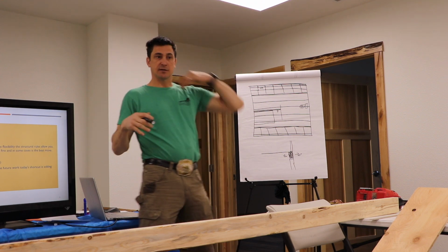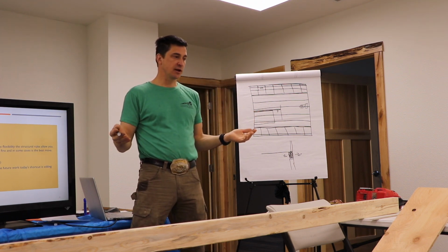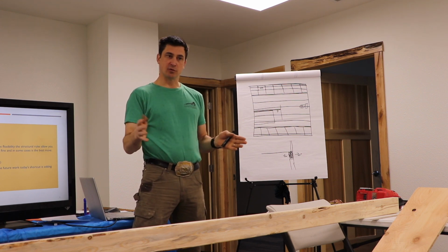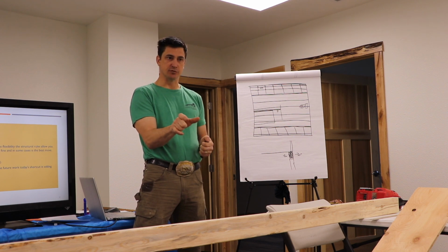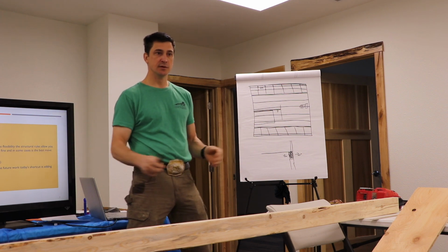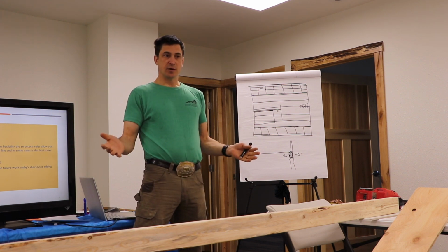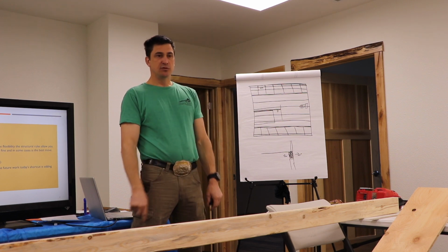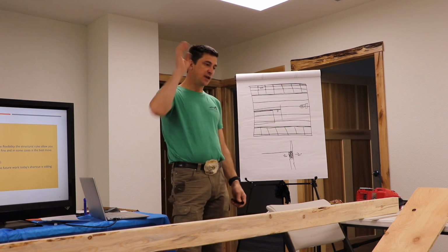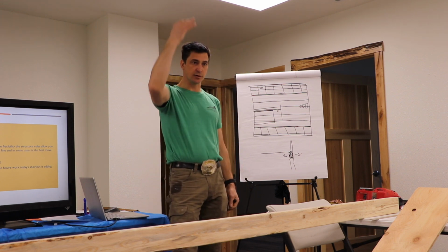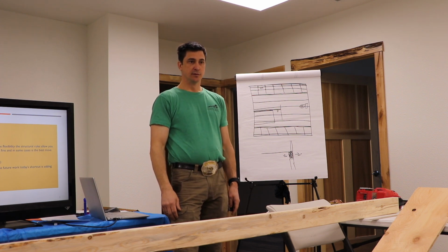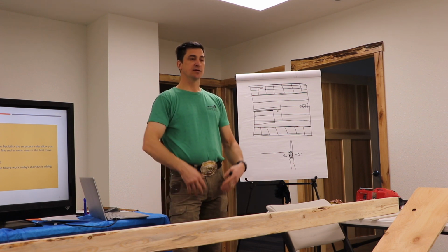Like the typical way the industry ran when I was your age starting out, every single top plate had a 2x4 or 2x6 on it that stuck out 1.5 inches or 2 inches, so you had something to screw your drywall into. Every top plate in the whole house. So you'd take a 2x4 interior wall and you'd slam two 2x4s down on top of it, one to stick out each side. Every gable end, every corner, we put heaps of backing wood in, right? And it adds all kinds of time and it gives you a worse product.